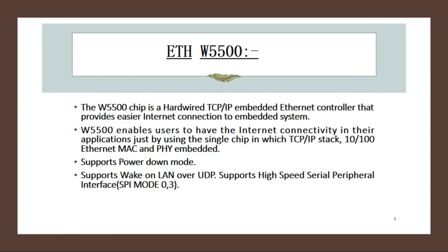about the W5500. The W5500 chip is a hardwired TCP/IP embedded Ethernet controller that provides easier Ethernet connection to embedded systems. W5500 enables users to have internet connectivity in their applications just by using a single chip in which the TCP/IP stack, 10/100 Ethernet MAC and PHY is embedded. It supports power down mode, supports wake on LAN over UDP, supports high speed serial peripheral interface, the SPI mode 0, 3.